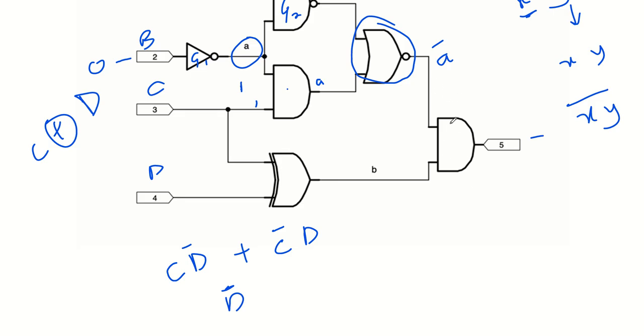Now, A is the one which is changing the output, so you have to fix the output here towards 1. It means that we have to assume this gate, let me call it gate 3, is always outputting 1. To be able to do that, given our conditions, D has to be 0, so that D bar will be 1.